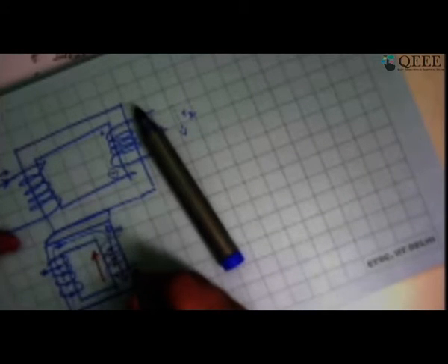So I am having the dot here and dot here. This is what it is. Are you getting my point? So I have to look at the current orientation and the winding orientation such that the primary flux and the secondary flux oppose each other. They cannot aid each other. As simple as that. That's all is the basic orientation of these windings and the flux respectively.